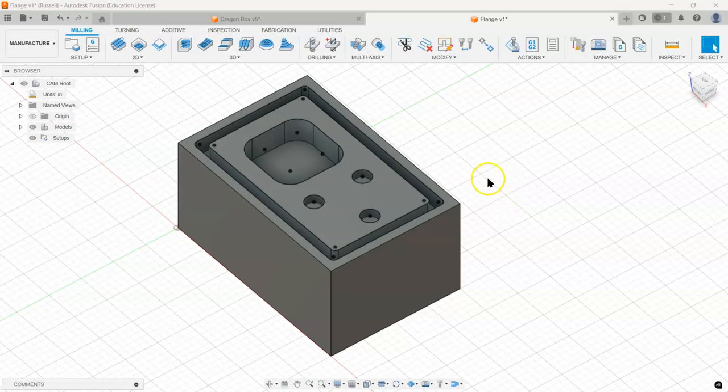So you kind of have to play with it and see. If I don't do a tool change, the trade-off is that I'm going to have to use a smaller bit because this looks like my smallest dimension, which means I've got to take more passes in here. But if that difference is less than what a tool change would add in time, then I'm better off just taking more passes. And really the only way to do that is to find out what your time is going to be.